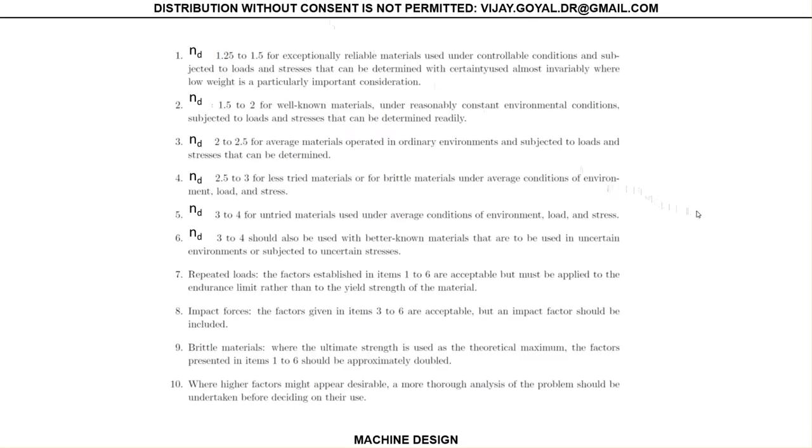Again, you're more than welcome to pause this and go over this material. These are some typical design factors. Typically, the range is 1.25 to 5. Very commonly 1.5; if you don't know anything about the problem, you can just use 1.25. Many times, just using 1.5 would do it. Anything above 1.5, you're really talking about environment loads, or a very critical part to the business, to the problem you're doing.